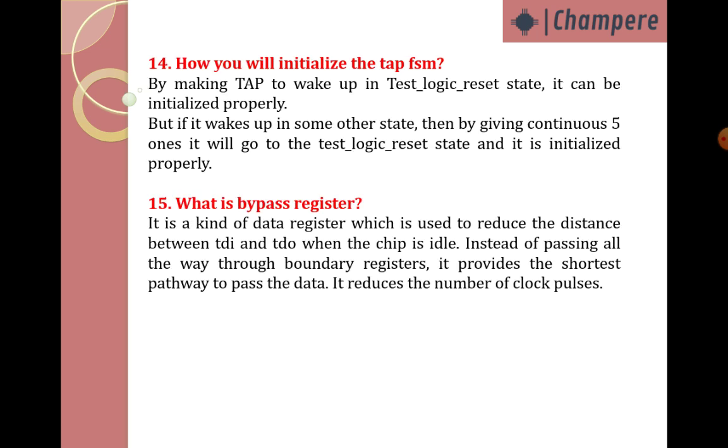Next question, how will you initialize the TAP FSM? Sometimes they will ask how you will initialize the TAP FSM. By making the TAP wake up in the test logic reset state, it can be initialized properly.